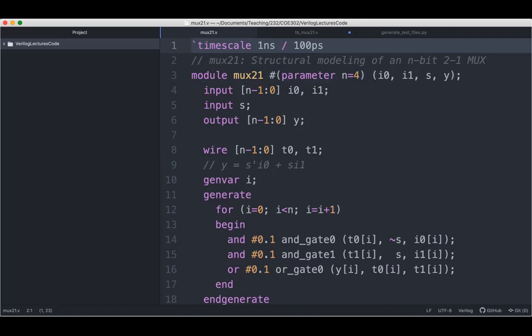Next is, if you want to define any circuit in Verilog, it is a must that you embed it inside what we call a module. Okay, module is the basic entity that embeds circuit structures. Here we give the module a name. The keyword module starts a module definition, and then a space followed by the module name.